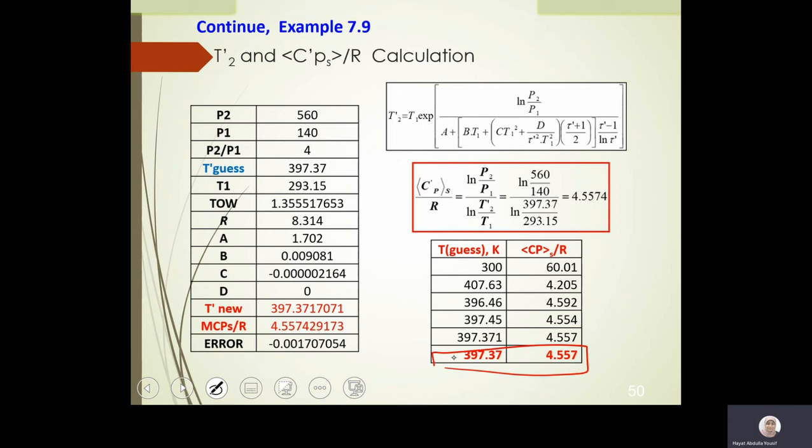I just substituted, but to convert the final result into kilojoule per kilogram, I had to make conversions, which you should be aware of, because the pressure difference is in kilopascal, while the specific volume from the appendix is in cubic centimeter per gram. So we just had to make these conversions. This allows me to calculate the isentropic work. Sorry, up to here, it is the isentropic work, not the actual, and it is 11.57.